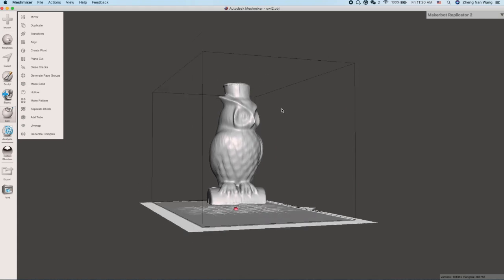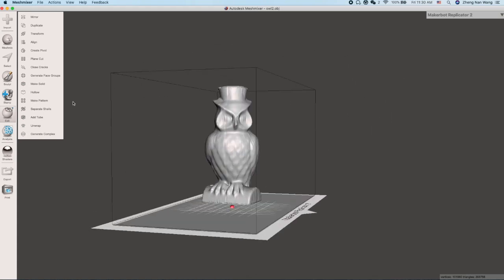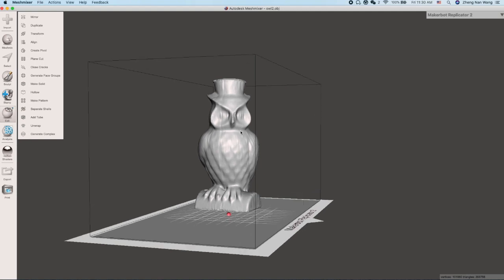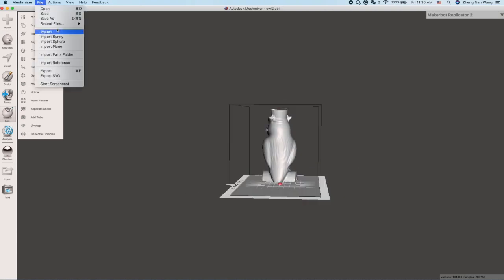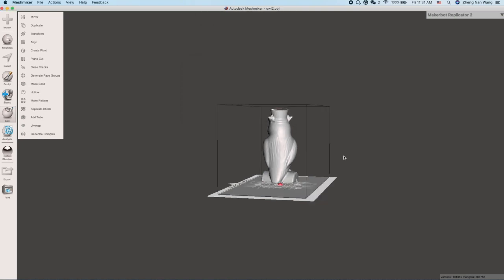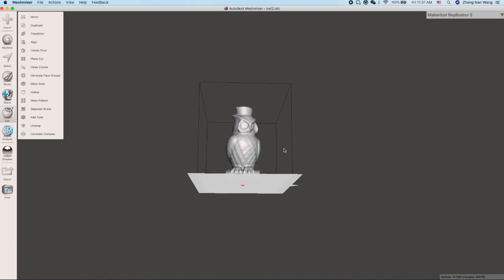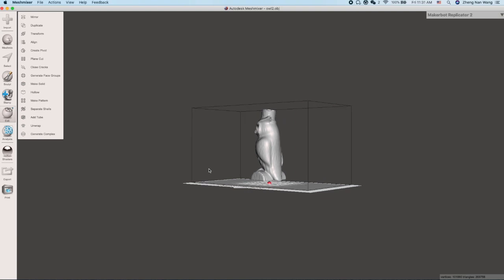And there you go. You basically cut out the top and the bottom part of your 3D model. And now this is good. And then we can just 3D print it. We can export it into an STL file. Okay, in the top, export, and then into an STL file. Let's call it OL3. Okay, and you click on save, and boom, it's done. So now you just have a nice solid STL file sitting in your computer ready for 3D print.